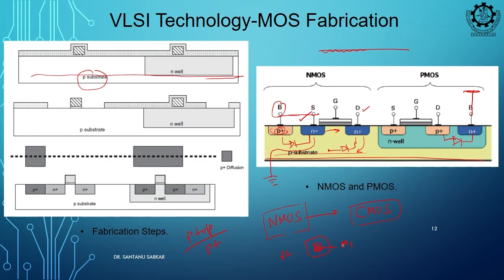So, that will act as a short for the P substrate, clear. So, this is a mask just to ensure that on the P substrate you have an ohmic contact. So, that P is connected to that metal. If you now carry metal 1, it will be a connection, that is it.